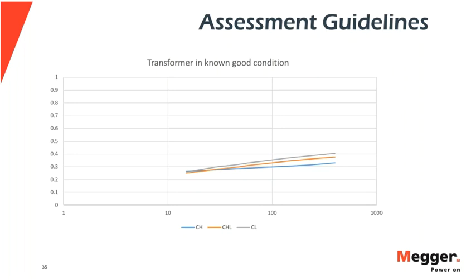Don't forget to double check the oil temperature at the time of test to make sure that these results have been compensated for temperature back to their 20 degrees C equivalent base. From there, I would comment that 0.3 to 0.35%, assuming that this is 20 degrees C equivalent data, is reasonable. So the next step is to verify whether that in fact represents good insulation systems. So we identify the slope of the response through that 60 hertz point, and each of the 3 are positive, which signals an acceptable condition.